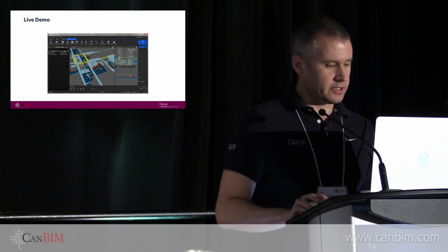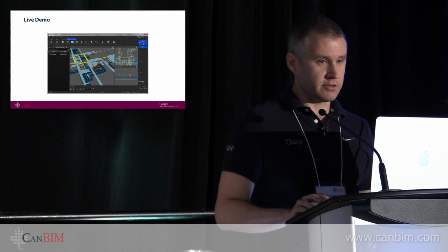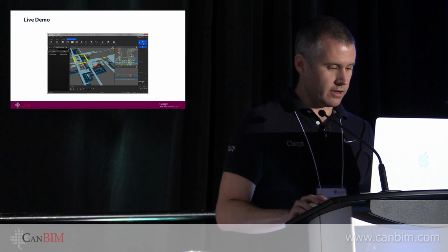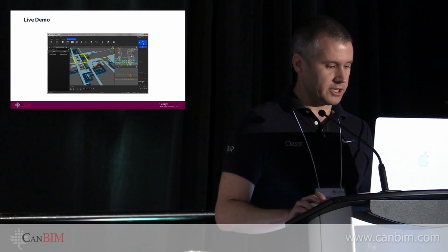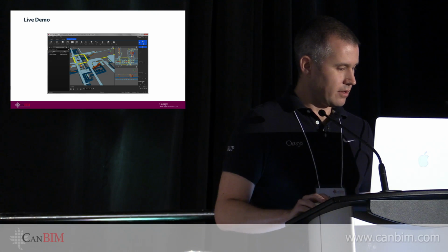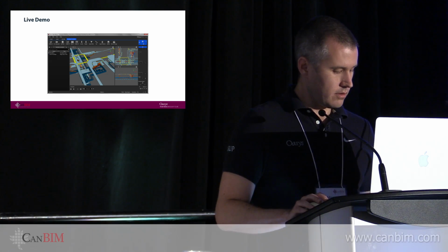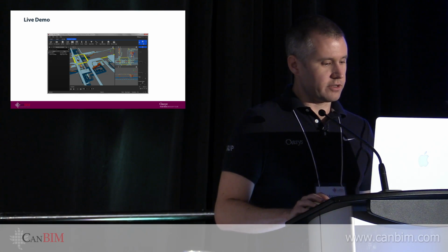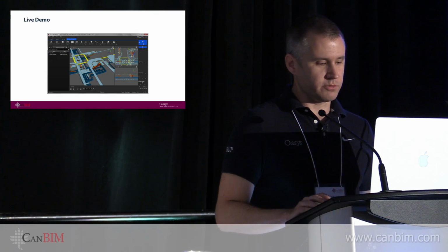The cool thing about IFCs is because there is metadata associated with all those objects, you can also go in, right-click on it, and say, I want to auto-generate all my objects in here. And so it goes through and knows that there are floors and doorways, and it solves all of that for you. So right away, you've gotten probably 90% of the way there in terms of the geometry that's necessary for the simulation.